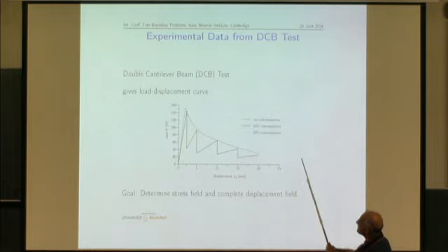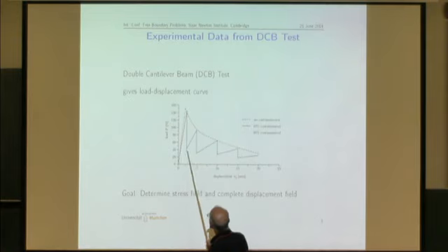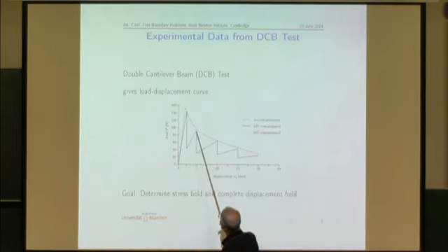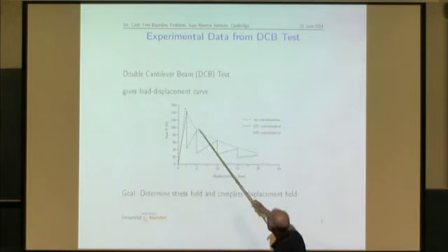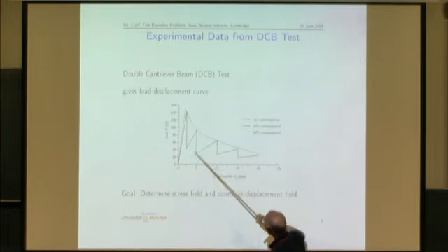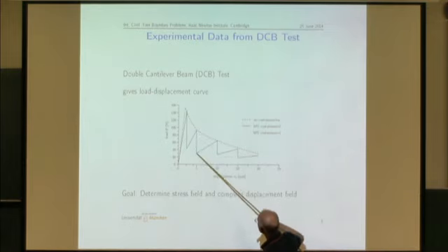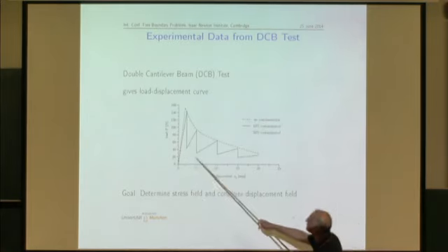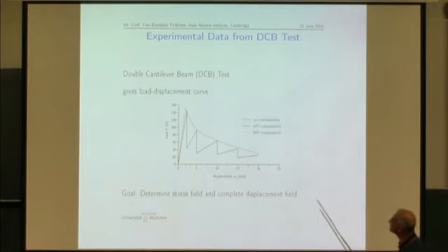And then you pull constantly. You pull the specimen, and then with this decreased load, the crack propagates again until this critical load of, let's say, 90 Newton. Again, the crack stops here, and the observed load jumps down to this level of 50 Newton, and so the story goes on. These jumps continue until you observe a total failure of the structure.